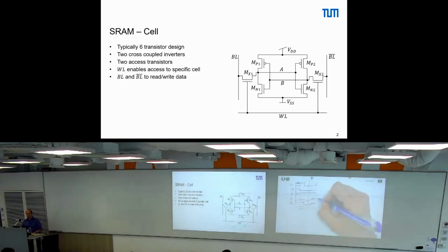A is on a different level, or differently charged, compared to bitline, yeah? But it's connected to bitline. So what will happen is that A goes a little bit up. Probably I use another color to make this better visible. So this here goes a little bit up towards VDD half. The bitline will, because A is 0, go a tiny little bit towards 0. Not fully.